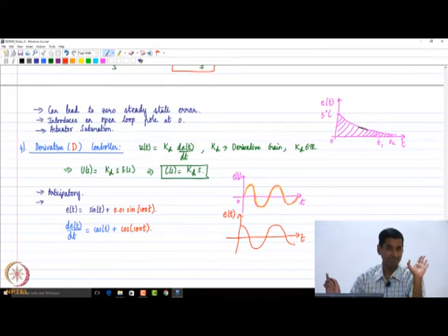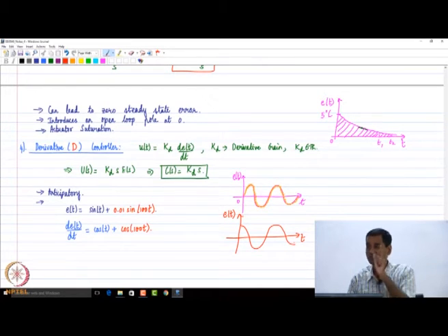That should have been my ideal derivative signal, which should have been the control input. But what is cos 100t? An extremely fast cosine signal, and cos 100t is going to mask this cos t. Do you agree?